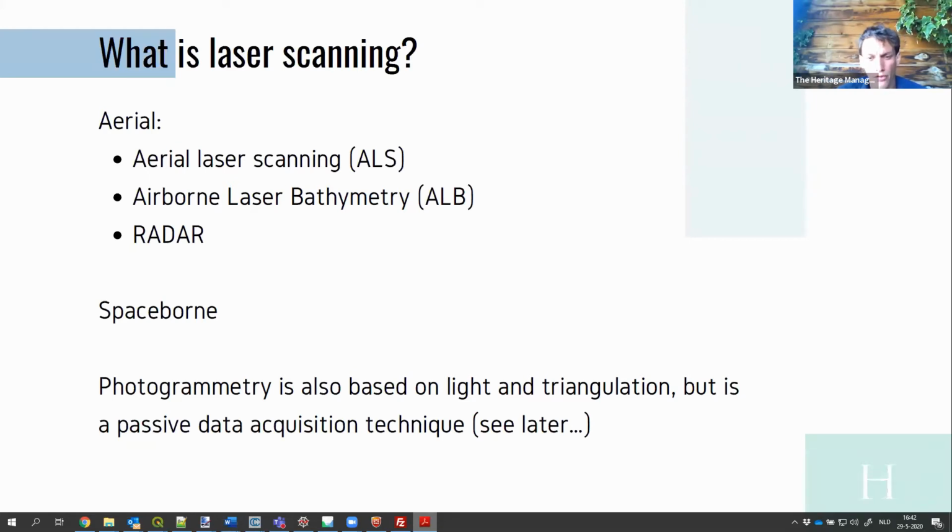I'm from the Netherlands, and I live in Belgium. We have the North Sea as our neighboring sea, and for the North Sea, I would definitely not implement laser bathymetry because of turbidity. But if you're living in the Mediterranean area, or in the Baltic Sea, for example, where most of the first papers were written about applications, the water is very clear. These are very interesting sites to use laser bathymetry.